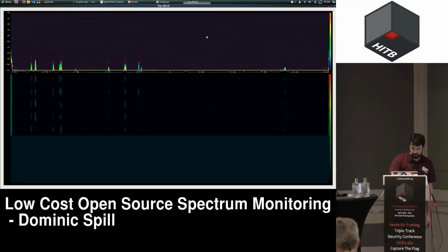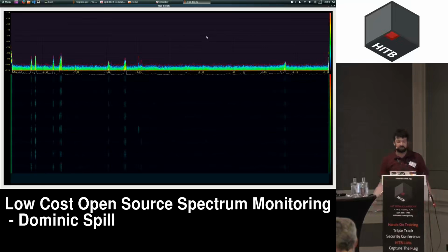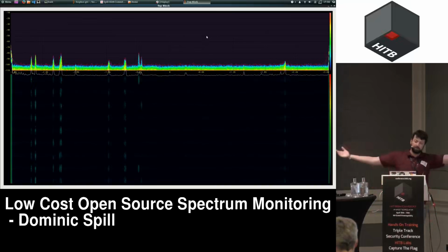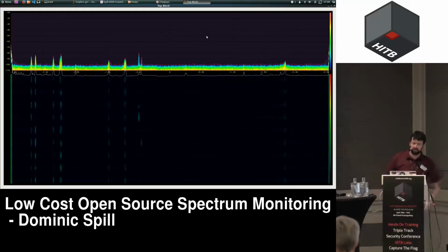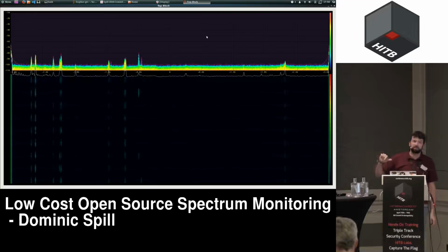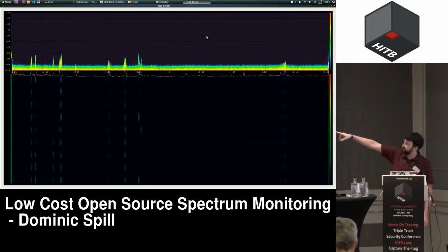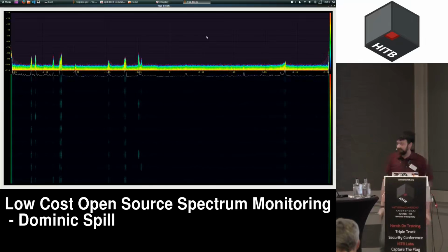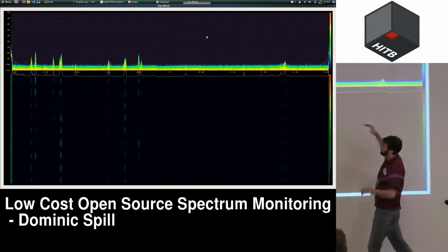And so what we should be able to see now is, again, doing the same thing, and it's sweeping over 6 gigahertz wide, and it's performing an FFT over every 500 kilohertz, and then plotting that using GR phosphor. So you'll probably be used to this if you've used software-defined radio in the past couple of years to look for signals. This is very good at showing you transient signals, and we can see the 2.4 gigahertz section again. We're looking at 6 gigahertz wide here.